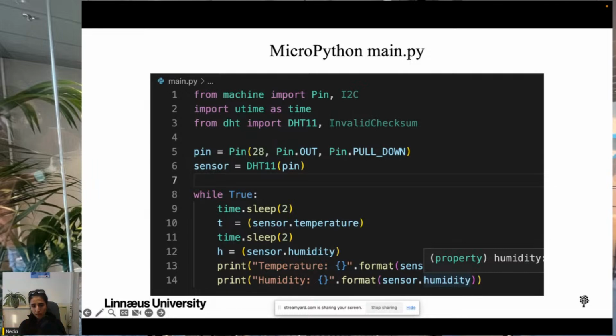In the case of a GPIO pin, actively driven means that the microcontroller is either setting the voltage level on the pin to high, I mean 3.3 volts, or low, 0 volts, or is rapidly switching the voltage level between high and low to create a signal or data transmission.